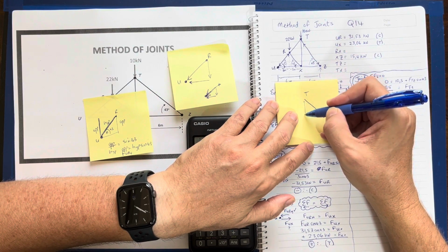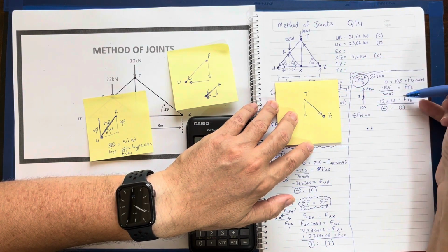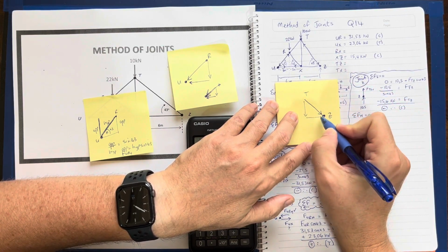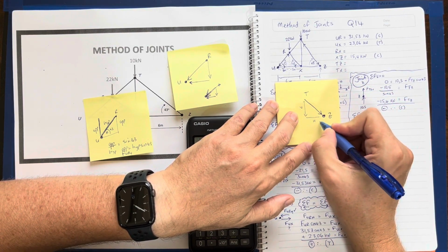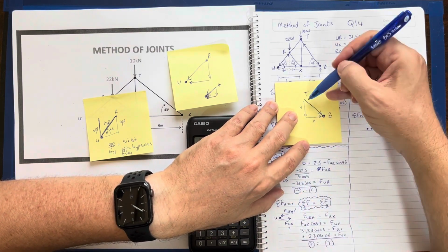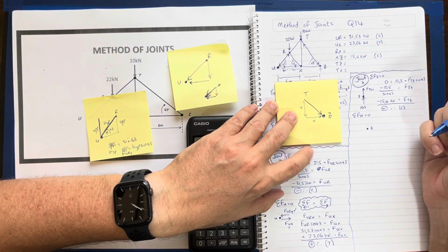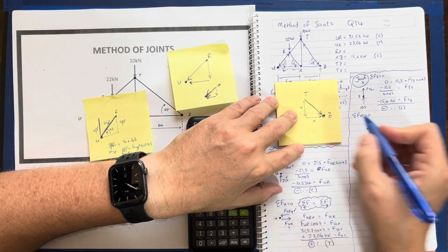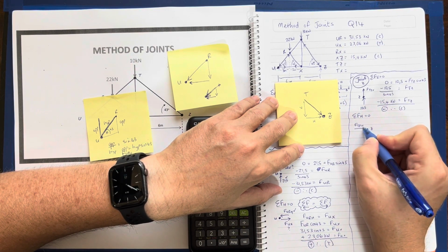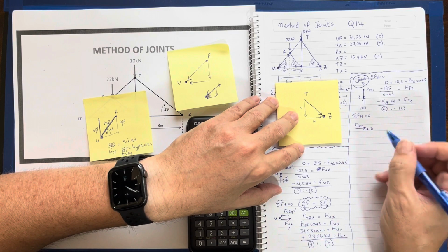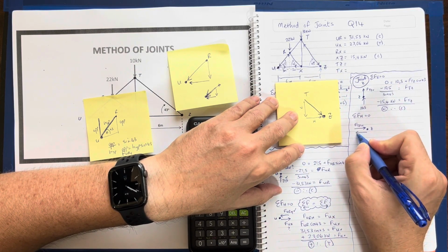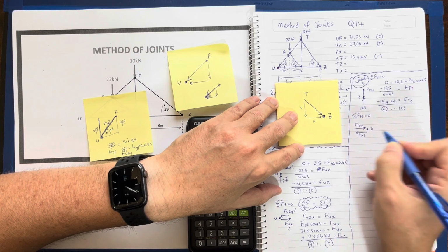I worked out already that if it's doing that, the resultant vertical and my resultant horizontal have to be traveling in that direction in order to make the resultant of my hypotenuse that. So I know straight away that the force TZ horizontal will be going into the joint. But I don't know what XZ is. Force XZ, that's my question mark.